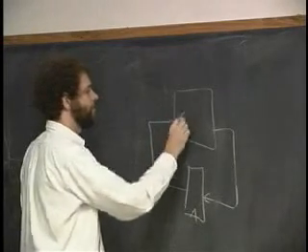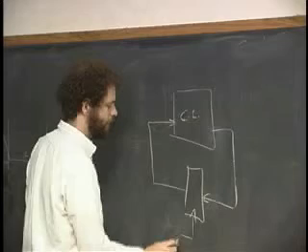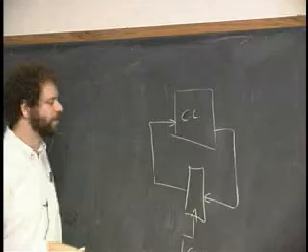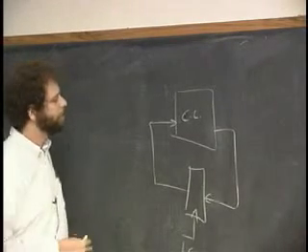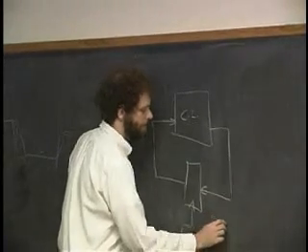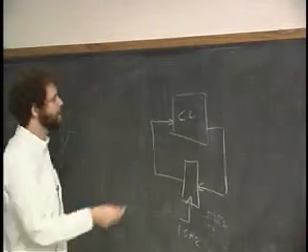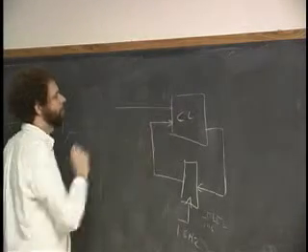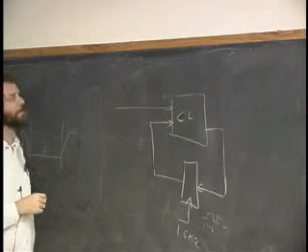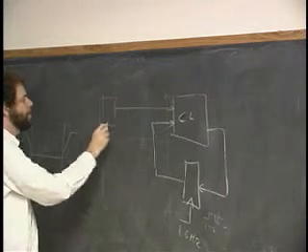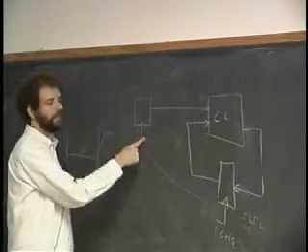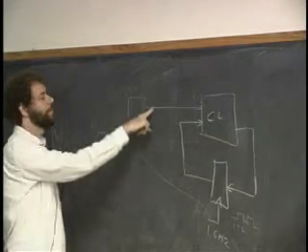Here's your FSM, combinational logic. And let's say that we're going to clock this at 1 gigahertz. Okay, this is on the inside of the Pentium 4 or something, right? It's actually 1.5 now. Let's say 1 nanosecond in between pulses. And despite their attempts to make it not so, there are actually real-world inputs to the Pentium 4. How are we going to deal with it? I'm telling you that if there's a register here, and we clock this with the same clock as here, we have to wait 100 clock cycles before we can make use of this output.